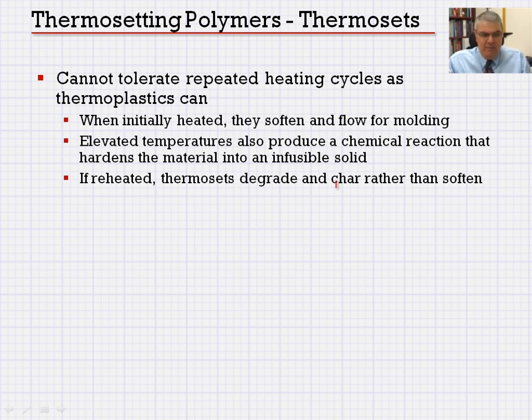If we reheat that, then thermosets, unlike thermoplastics, degrade, and they char rather than soften. So it's very important to realize these characteristics of TP versus TS, which is a symbol for thermosets.